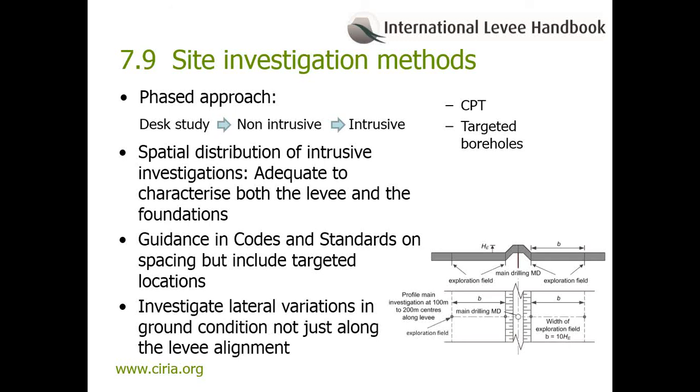Fundamentally, the spatial distribution and depth of the investigations have to be sufficient to characterize both the existing levee and the foundations. However, spacing should not be driven by the concept of a fixed spacing, but balanced with targeted locations based on ground features identified in the information available at the time, with desk study, non-intrusive and earlier intrusive investigations.